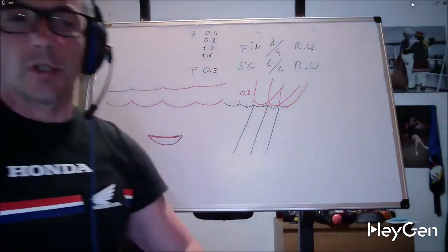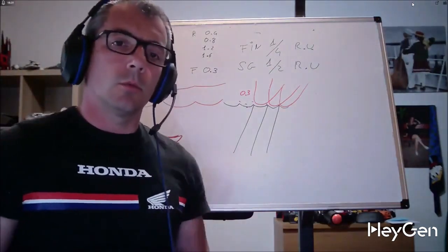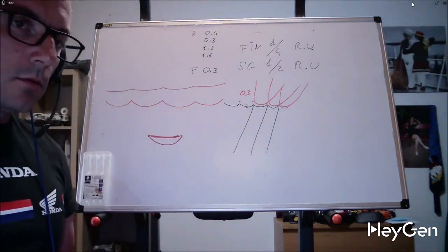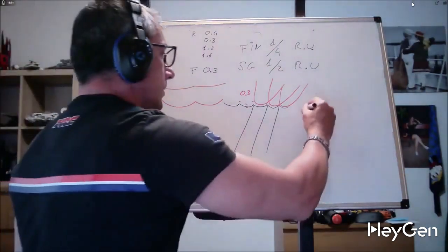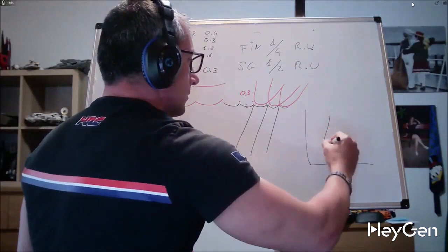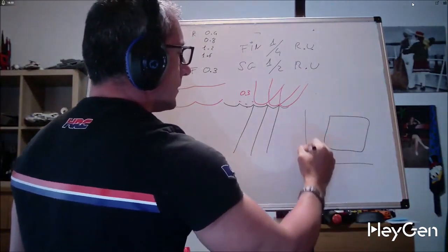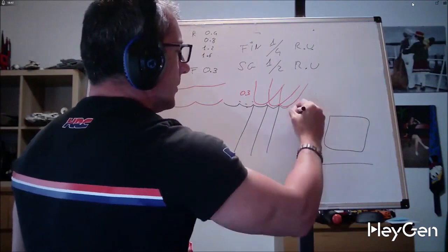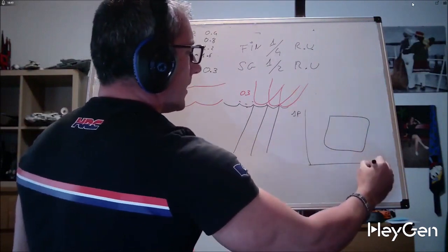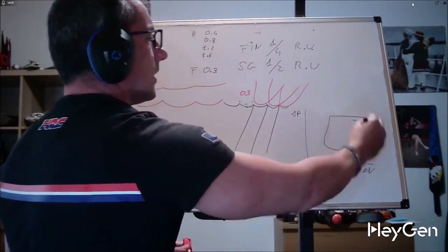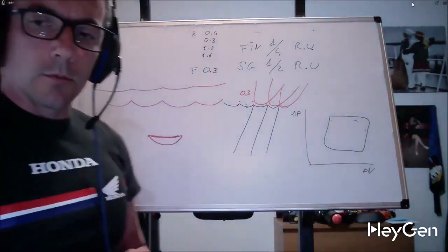That said, each tool catalog includes a small chart with a drawing that shows the depth of cut on one side and the feed rate on the other, and you need to stay within this little graph. Make sure to have it explained well. Look at your catalogs and you will find it. However, it is important to understand how roughness works and to have an idea.